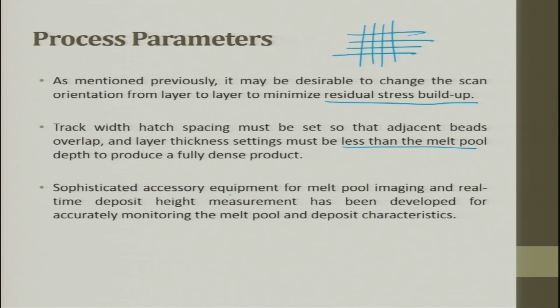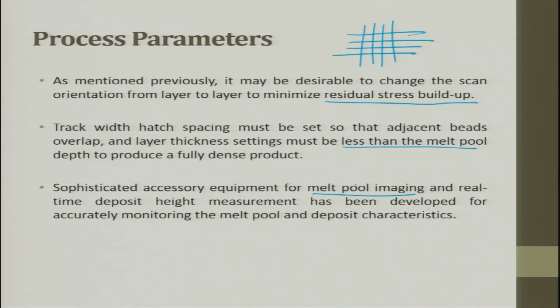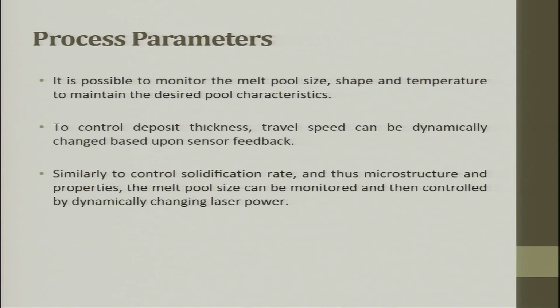Sophisticated accessories and equipment for melt pool imaging and real-time deposition height measurement have been developed. What is the temperature at the melt pool? Because if there is a larger melt pool, it is going to create more melting and solidification, and we now have to balance it. And the other thing is, whatever happens when it solidifies, it does not give you uniform height or thickness. So, we need to measure the melt pool temperature using imaging techniques and measure the real-time height, so that we know what powder flow is to be given.